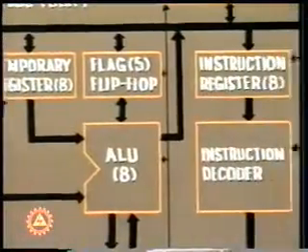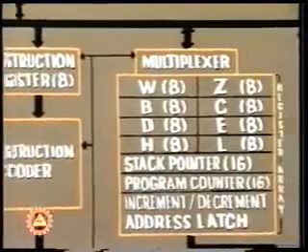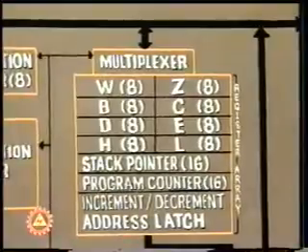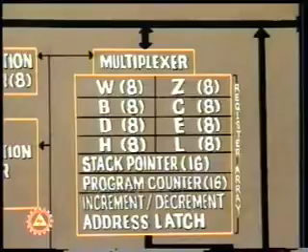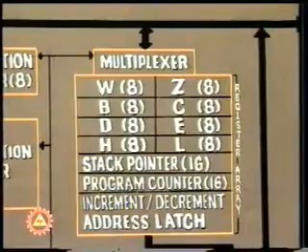In 8085A, stack operation push and pop uses 2 bytes, and so the stack pointer is incremented or decremented by 2 after each stack operation.